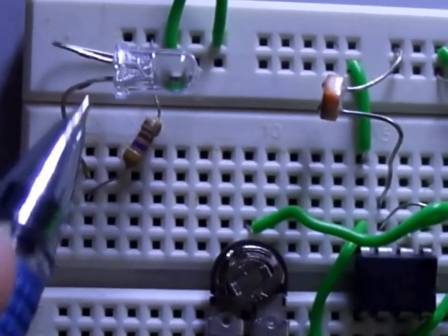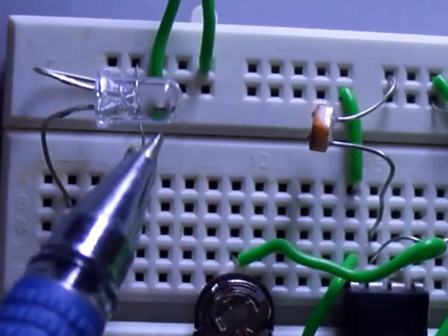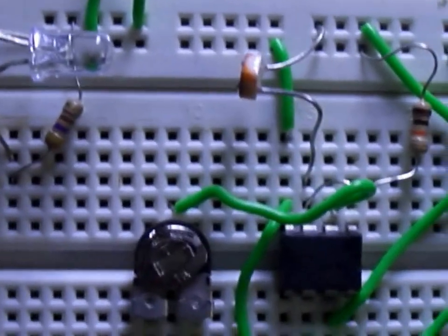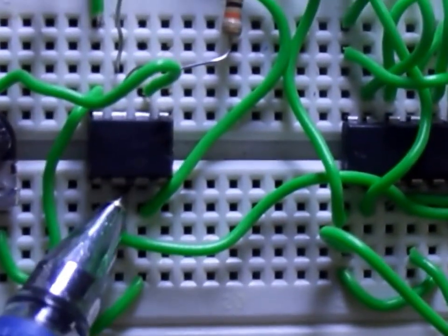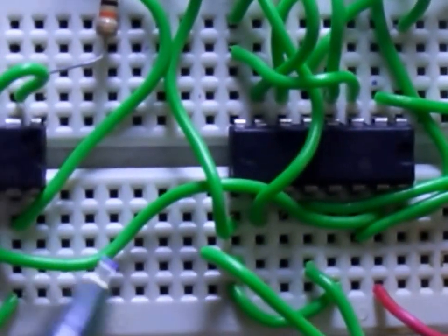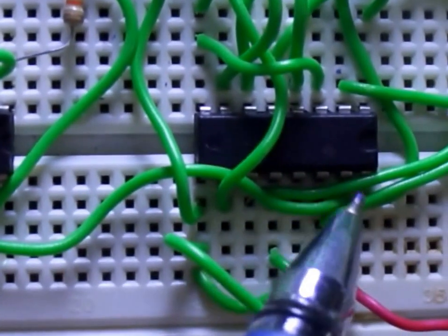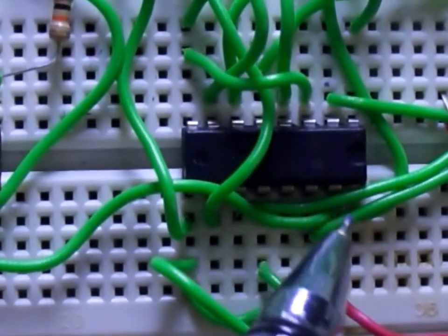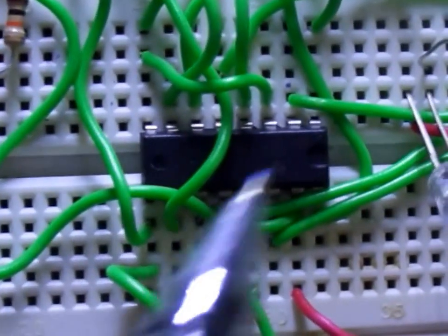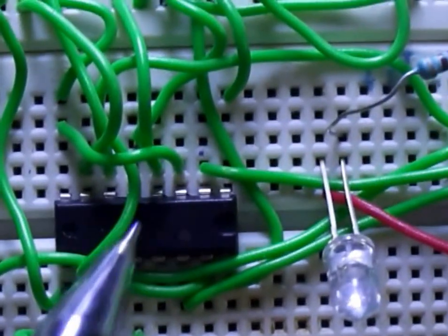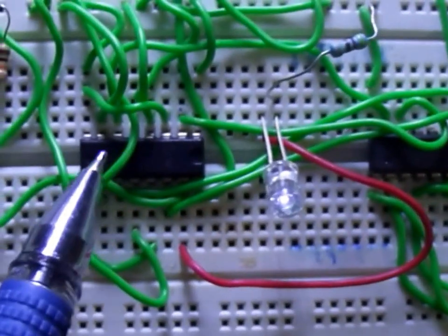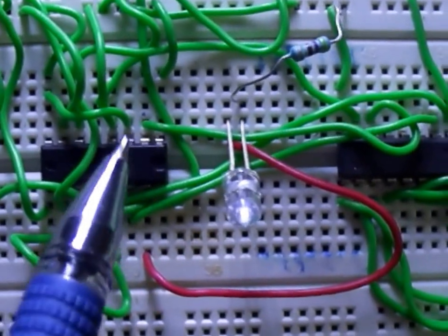It is connected so that the LED will not be destroyed or damaged due to high current flow. So this resistor will limit the current flow. This is pin number 6, and from pin number 6 the output is going towards this processor. The processor is getting the clock signal, and this is pin number 15, that is the clock signal of this processor, or the IC4510. And I won't go into detail of these connections because I have already shown you in the simulation and the schematics have been discussed before.